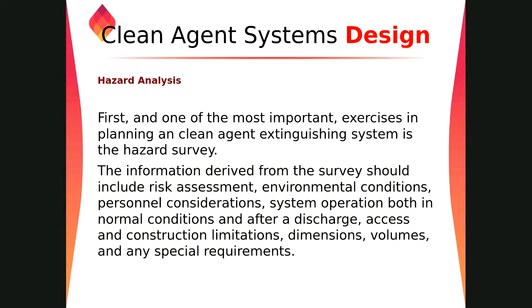The first step in planning a clean agent system is the hazard survey. Go to the site, see what needs to be protected and what the criteria are. You can get that information from the survey. You should include risk assessment, environmental conditions, personnel considerations, system operation, normal conditions, and after the discharge, access and construction limitations. What is the volume of the room? What is the special requirement? Everything you have to check at the site before designing your system, right? What is the volume? Where should I keep